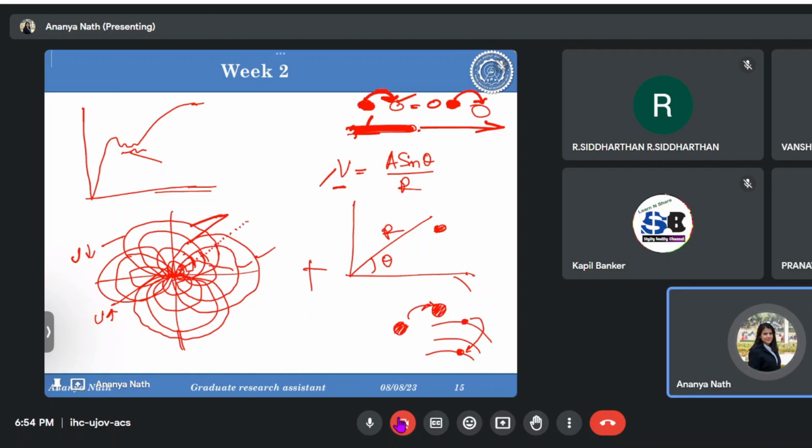This movement comes under the Cottrell-Bilby theorem. First the equipotential lines were introduced using the interaction energy between dislocation and the solute atoms. But after that, when using the different energy gradient, the solute atoms were moved through the different energy gradients. So dislocations were moving perpendicular to the direction where solute atoms were moving. That's why these perpendicular circles are again made. Also, a lot of circles are made depending upon which favorable conditions they were given. It's like that.